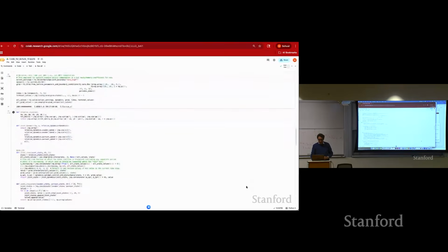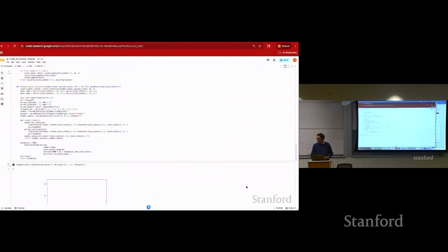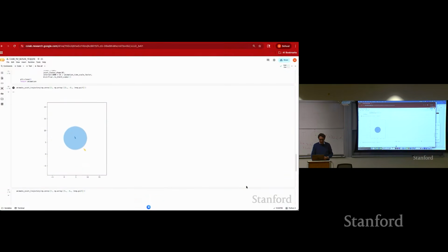Let me show you some examples. You do this computation, you compute the control profiles, and then you start injecting some possible initial conditions. Here I picked 3 for fun. Blue is player 1, red is player 2. We want to make sure that player 2 doesn't enter our personal space. So here is a situation where we started, in terms of relative coordinates, outside of the backward reachable set. No matter how hard player 2 is trying to play the game to catch us, it can't.